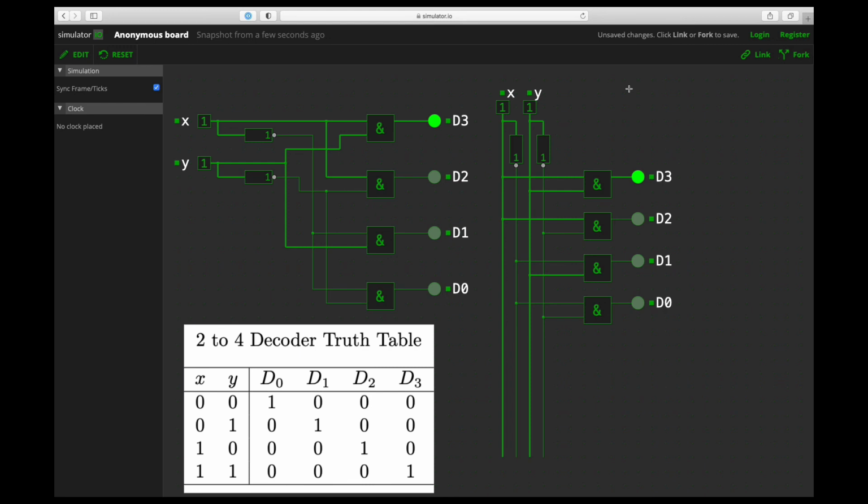We have programming languages for these kind of things. Verilog and VHDL are two programming languages that basically take these truth tables and spit out wiring diagrams like that, because it is not hard but tedious. So that should give you enough information to understand many of the circuits that we'll see, and also successfully complete the assignments I'll give you when it comes to actually wiring these circuits up.